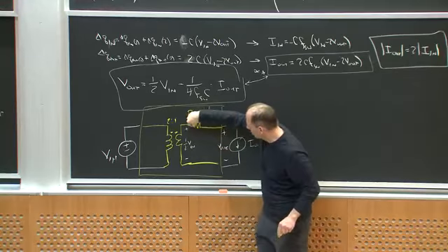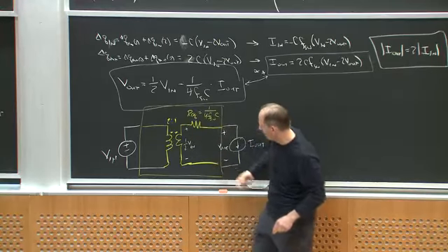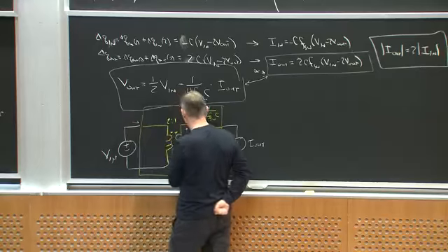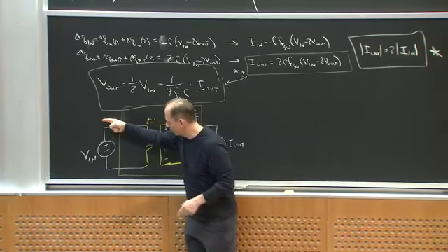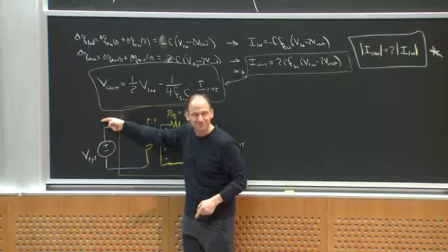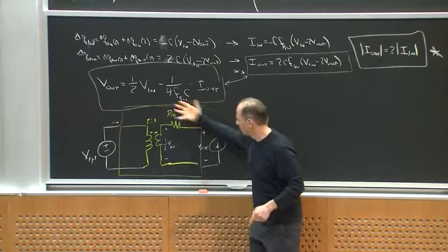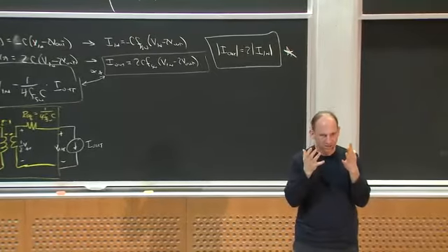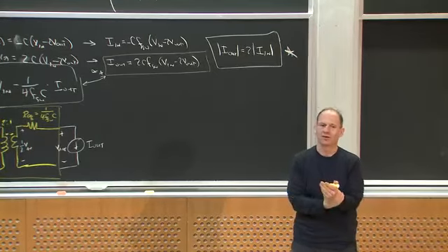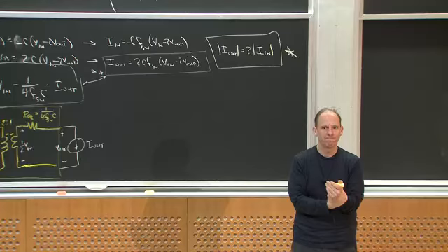Likewise, if I have a current coming I out this way, the current this way through the ideal transformer is going to be exactly half of that. And that means the current this way is minus 1/2 I out. All right? So this model in yellow here precisely captures the average circuit behavior of this system. Does that make sense to everybody?